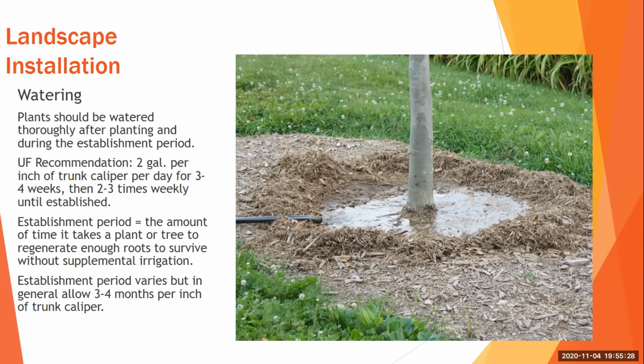That makes sense because grass and trees have different types of water requirements. So you need a bubbler here, maybe you need a rotor here, maybe for the shrubs you need some drip irrigation. So every plant has different requirements.